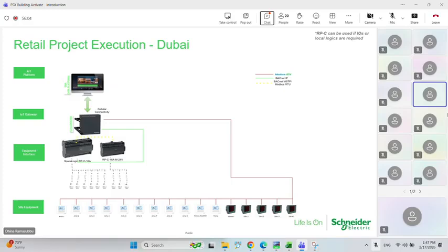If you see, there are four layers. One is the site equipment, where we simply put our thermostats and energy meters. Then the equipment interface, where we used two RPCs and pulse relays for the lighting control. Then there is one edge gateway, an IoT gateway, through which we use two different communications: BACnet IP for the lighting control, and Modbus RTU to integrate the thermostats and energy meters with the Flux server.